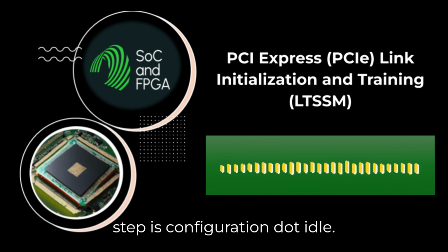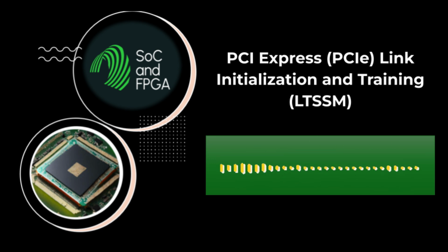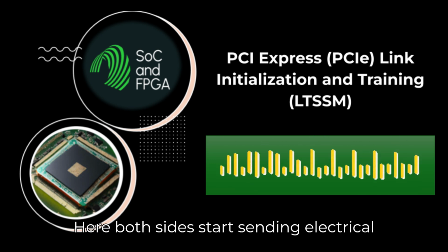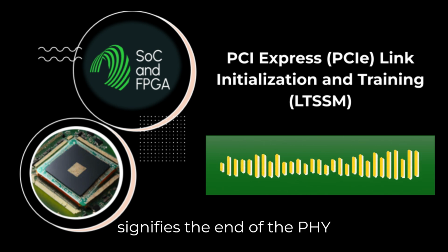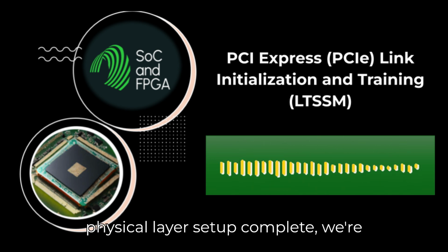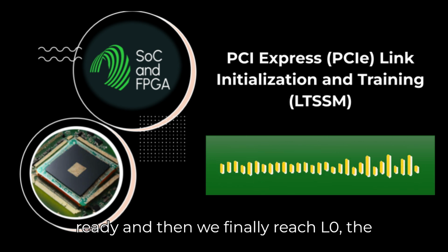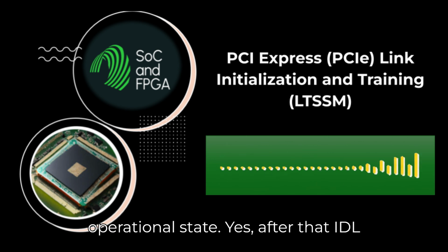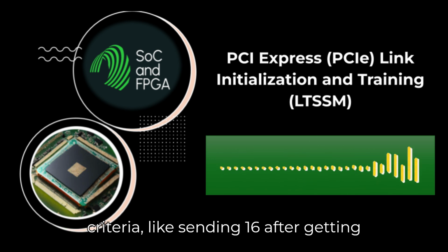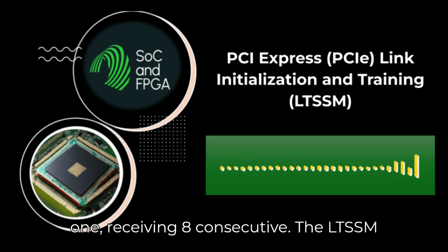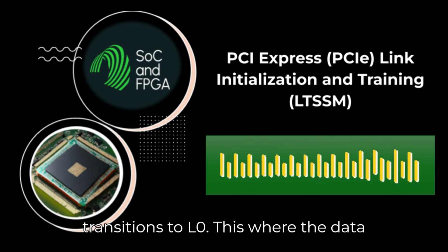The final tiny step is Configuration.Idle. Here, both sides start sending Electrical Idle ordered sets, IDLEs. This signifies the end of the PHY configuration. It's like saying, okay, physical layer setup complete, we're ready. And then we finally reach L0, the operational state. Yes. After that IDLE exchange, once Configuration.Idle meets its criteria, like sending 16 after getting 1 and receiving 8 consecutive, the LTSSM transitions to L0.